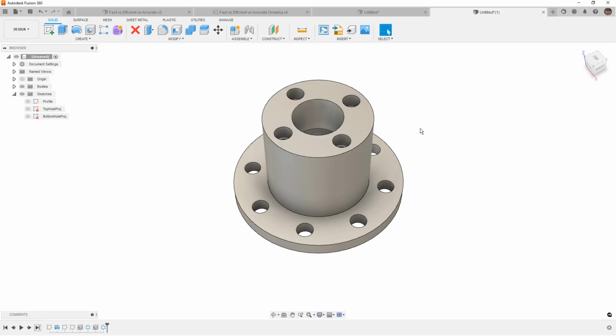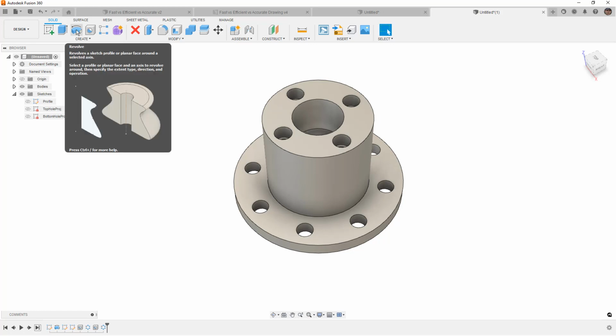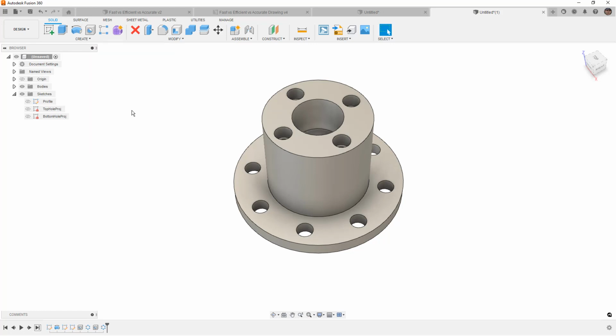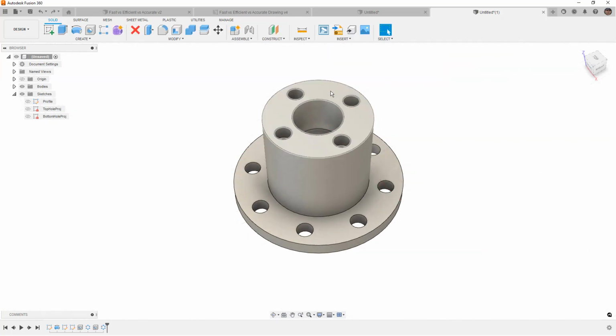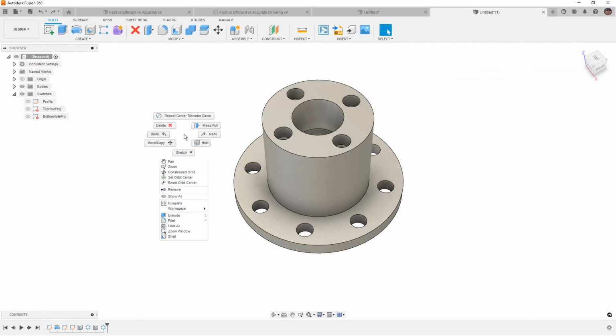There are instances where using a centerline sketch inside of a profile that you're creating will automatically grab the profile and the center line axis for the revolve. That's not true for things like lofts and sweeps, but it does work for certain tools like revolve. There are other things to know, like hitting C on the keyboard to start a circle tool, especially when you have a face selected, will automatically start that new sketch. Getting comfortable with the right-click marking menu. These are things that can make the modeling approach extremely efficient because it's going to be contextual.